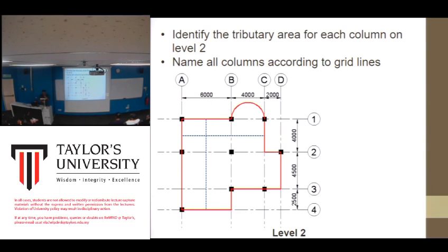The next one is slightly tricky, because here you have columns. So you look at these two columns. The half distance is between this column and this column, and then you stop there. And then this part, you look at the column between this and this grid line, because you have another grid line here. The other part just now is the same grid line, so here you have another grid line with a column. That's why you take the distance between these two columns. And then here you look at these two columns and these two grid lines basically.